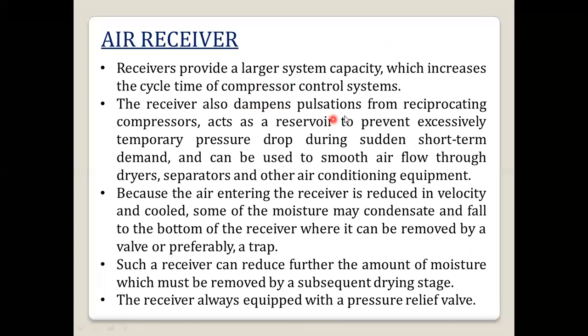The receiver also dampens the pulsation from reciprocating compressors. It acts as a reservoir to prevent excessive temperature drop during sudden short-term demand, and can be used to smooth airflow through dryers, separators, and other air conditioning devices. It dampens the pulsations from the reciprocating compressor, that is, the vibration is released. It will also prevent pressure drop.